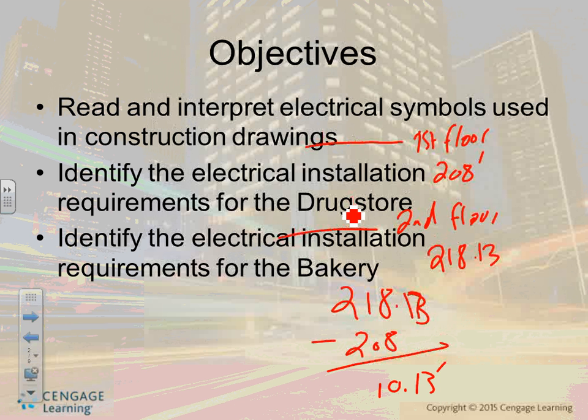Okay. Now, in addition to these 1, 2, 3, 4 views plus the top view, which is the plan view, in addition to these 5 views, they also have sometimes a 3D view. When you look at the building in 3D, you can rotate it. In addition to the 3D view, they also have sections. The sections, guys, is they cut the building in half right here. Saw the building, take one section out, and look and draw what you can see.